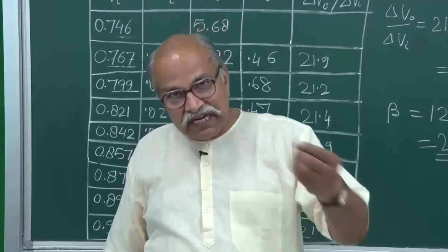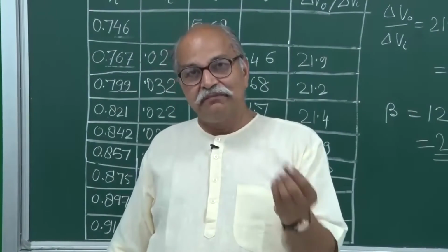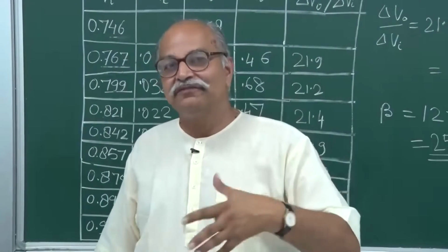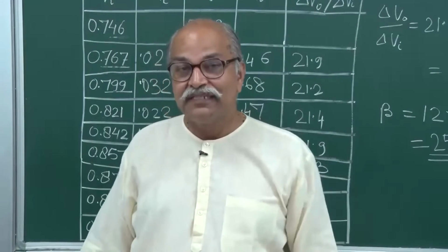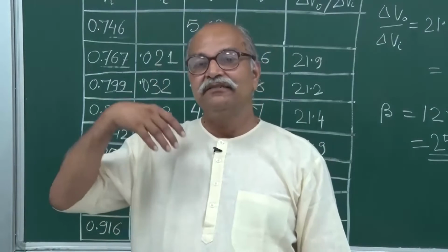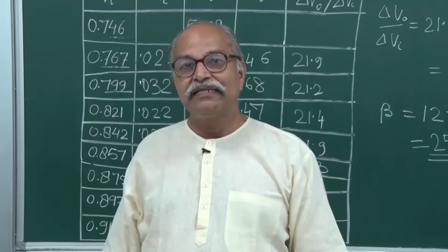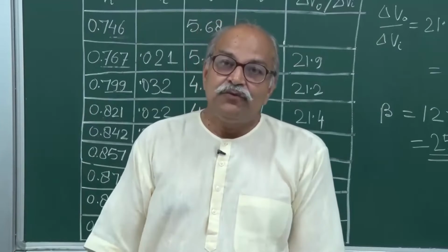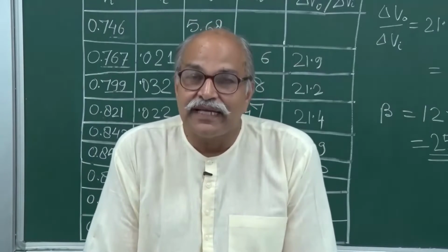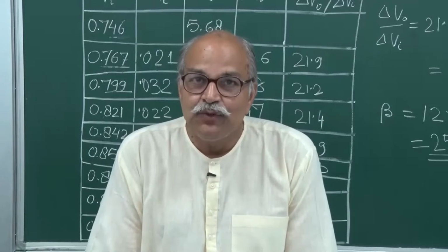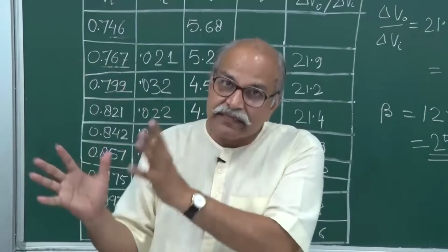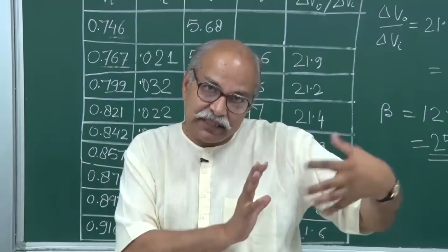The current that goes through the base part, that IB, is still a few tens of microamperes, whereas in that output part, the collector part, it could be 200 times more. So when we use a transistor as a switch, we control this output circuit through this input.